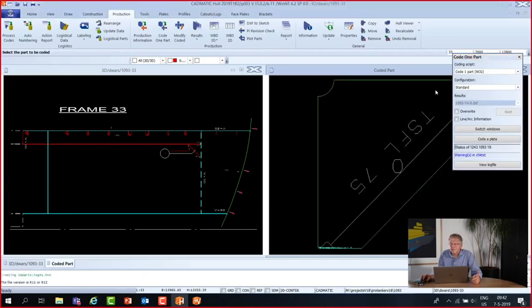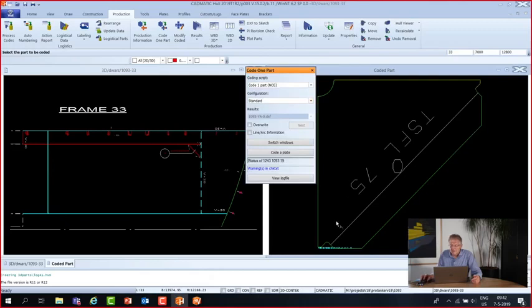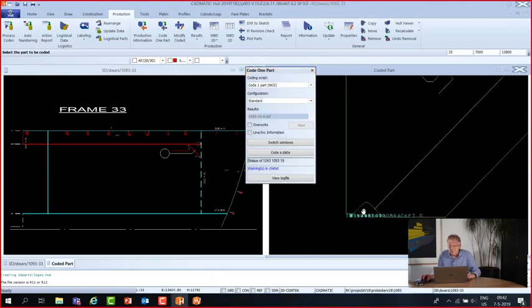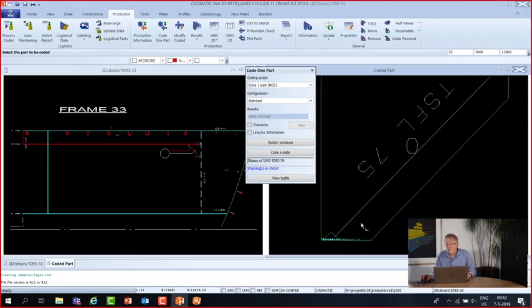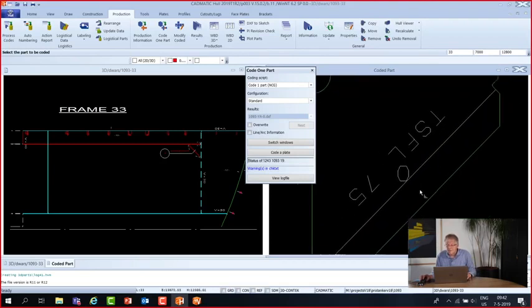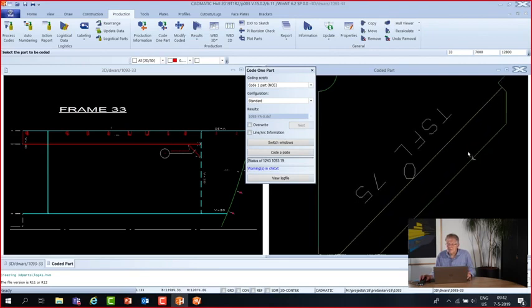Takes a while, but here we see it. We see the bracket including the flange, but what I'd like to emphasize a bit is that there is a radius here, meaning that it prevents cracking. So if the flange is bent, then there will not be a crack here in this corner. And what you see here is a so-called bending line. In this situation only one, there could even be 3: start radius, mid radius and end radius. And you see some text here, meaning this side flange 75 millimeters.